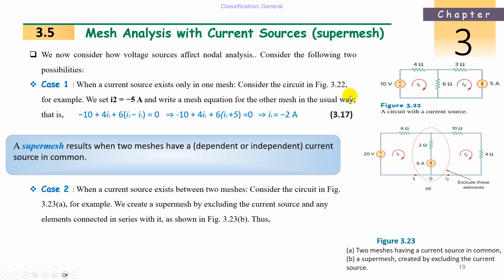Then we write a node equation for that. Already a loop equation is there, right? Node equation we also need, KVL and KCL. So like this, just remove this one. Just remove these two items and redraw the circuit. Then the loop equation will be the same, with I1 and I2, but just remove these two items. So this is called a supermesh.